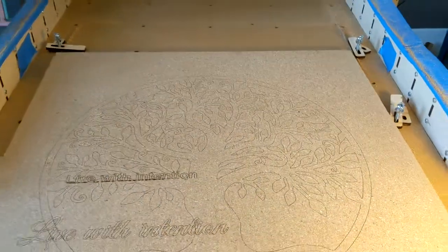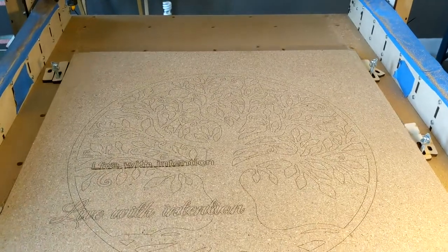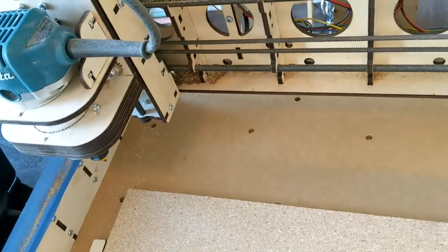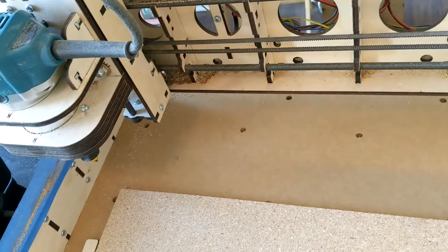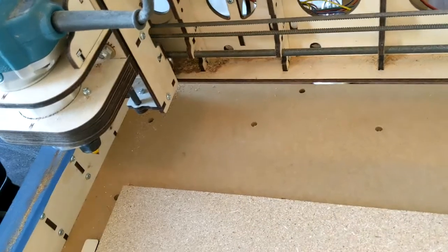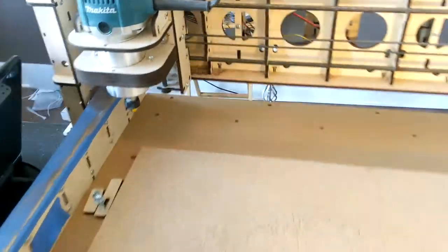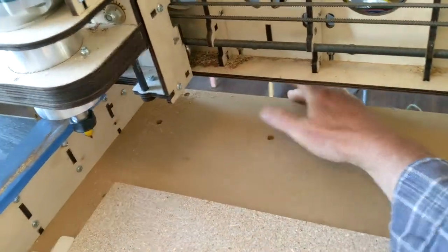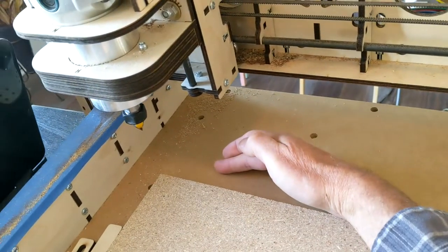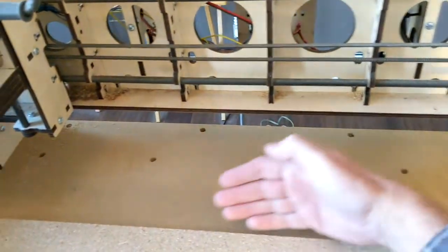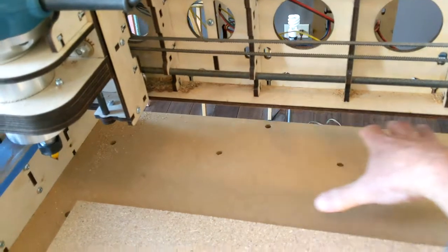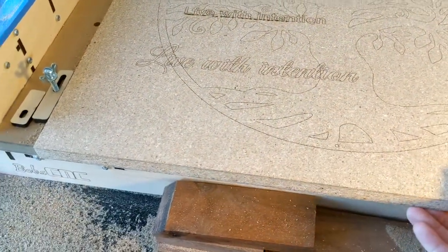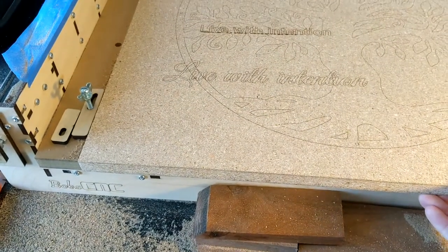Okay, so on Bob's CNC, one of the things I want you to take note of. This is Z home position, or I'm sorry, it's a complete home position. So we have on the E4 a huge unusable space. Literally, this is from here to here, 8 inches. None of this can have toolpath over it. So that's a little deception on this machine, but that's okay. You can hang your part off the edge.